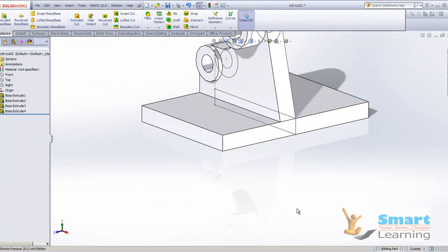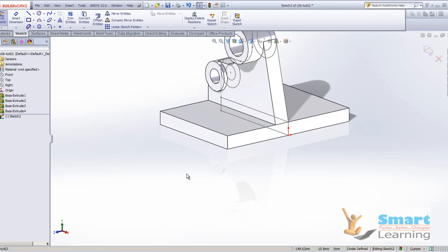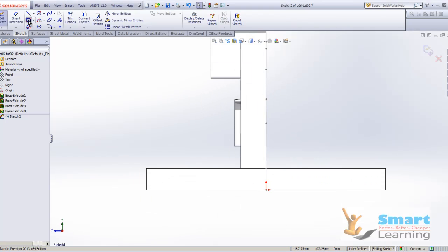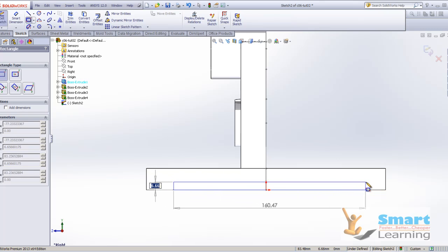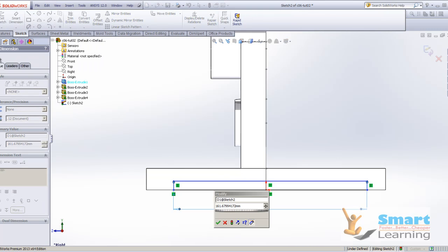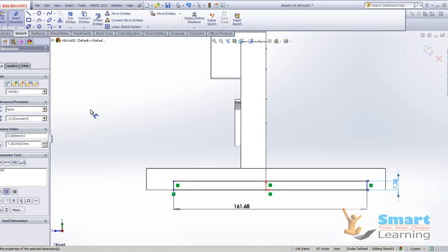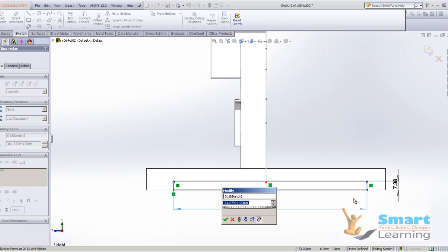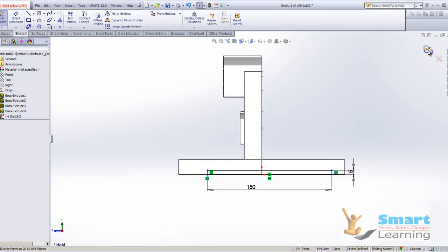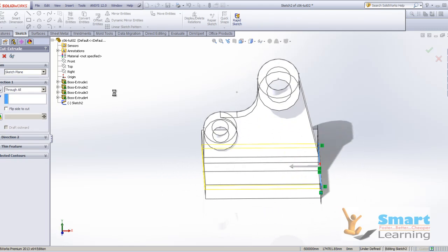After that you need to create a cut on this side, so we'll go to extrude, cut, and you have to select this face and press the spacebar, so that you can select this particular side, and you can prepare your required sketch which you need to cut, and you can define the dimensions here, whatever the dimensions you are looking for, and also this particular height you can specify. I'll just specify 150, and you can specify your dimensions. So arbitrarily I am just specifying. You can follow the drawings which are given, and here I can supply through all, and this will be done.